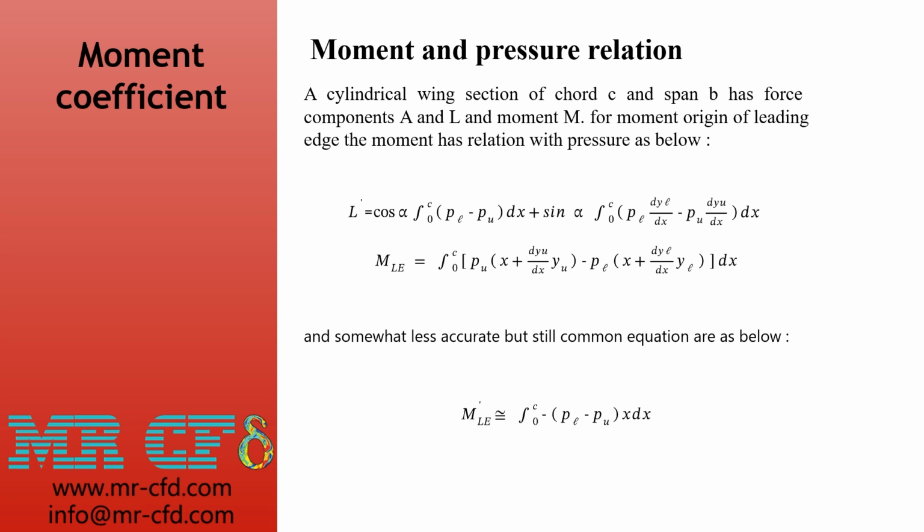So what Fluent does is it asks you to give a coordinate for the center about which you want to calculate the moment, and you give a number. It again uses a pressure integration to extract the pressure distribution, and using that pressure as a distributed force, it calculates the torque moment around the point given by you.